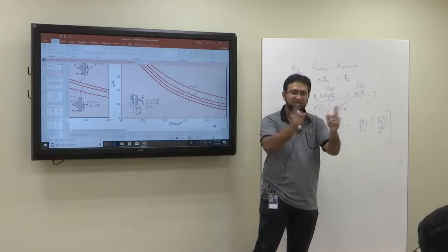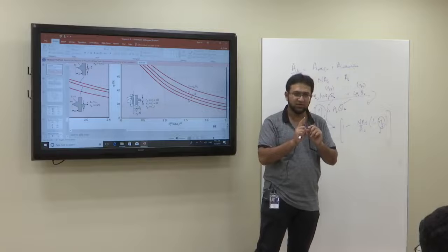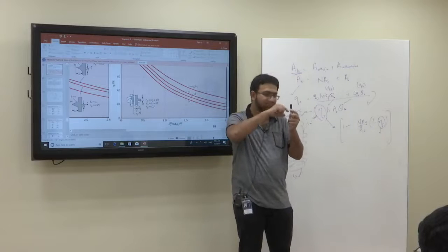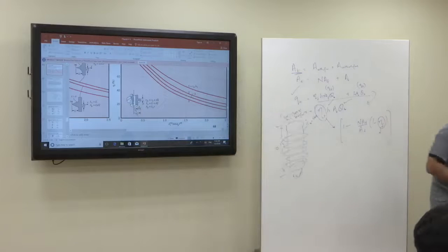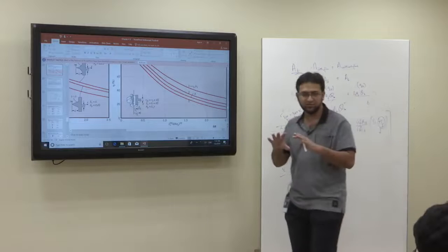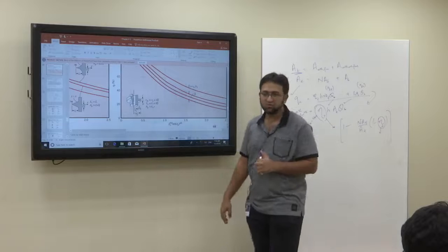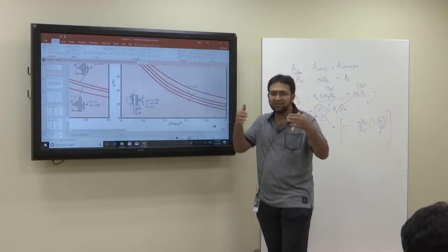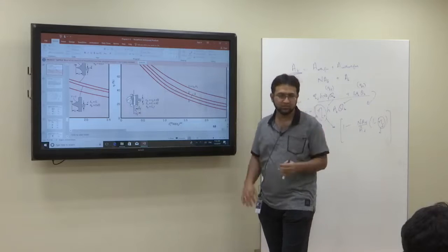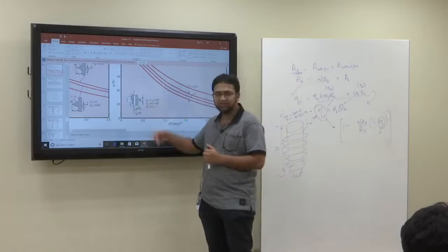These compensate for the tip heat transfer. If I have an annular fin, the tip of the annular fin will also be transferring heat, but I do not want to consider that. I want to add this into the length, into the surface area. So that's why I'm increasing the radius a little. That's the corrected length, the corrected radius.